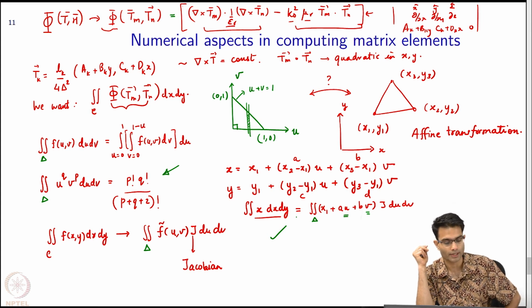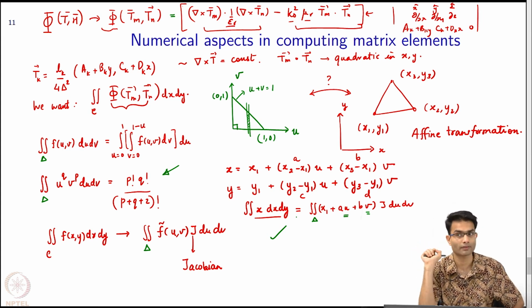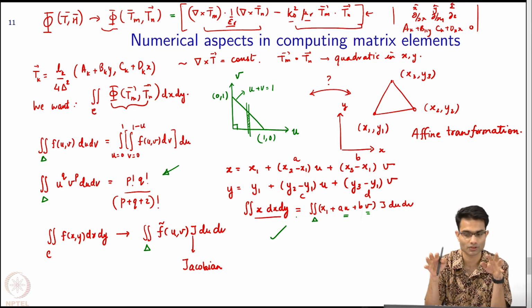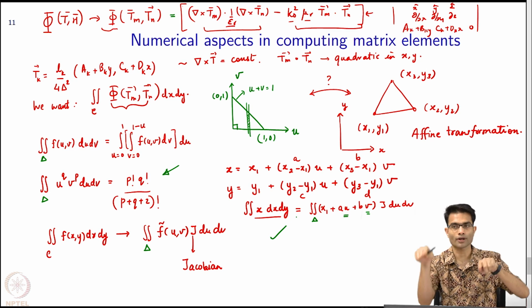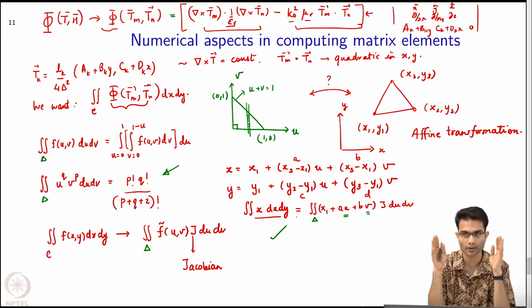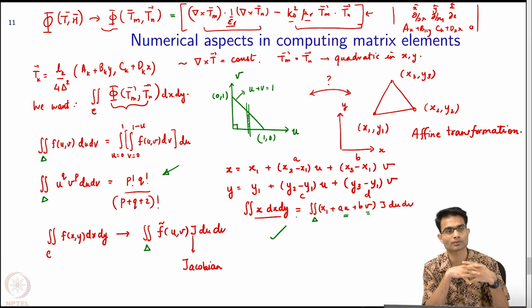It is very, very important when you get down to implementation that you calculate the Jacobian exactly. Don't try to take a mod of something in between, because the way the points are oriented, you may get a +1 or a -1 in the definition of the Jacobian. You should not try to put an absolute value over there, let it be what it is. That is the source of a lot of coding mistakes.